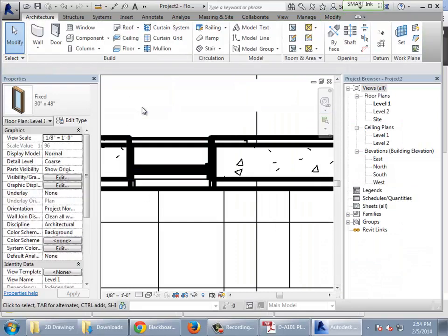Okay, that's probably pretty close. So in terms of my procedure, notice I'm approaching it this way. I start with the walls, and I'll figure out the wall types. Before I put every wall in, let me figure out the walls that are in my toolkit, the things I'm likely to use on this building. Because the truth is, architects are really repetitive. They'll choose two or three major wall types and repeat them throughout most of the building.